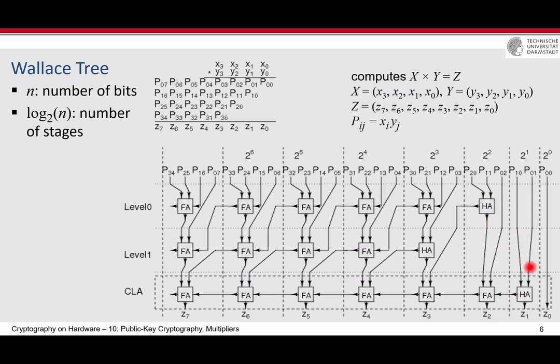half adder, and then the carry of every part goes to the next layer. It means the carry of this goes to the next layer, and then in this case you have 0, 2, 2, 0, and 1, 1, and the carry coming from the last stage. And it also provides 2 carries. These 2 carries also go here, with 0, 3, 1, 2, 2, 1, and 3, 0, and 2 other carries coming from the previous stage should be added together, and you see it generates 3 carries, and so on and so on.